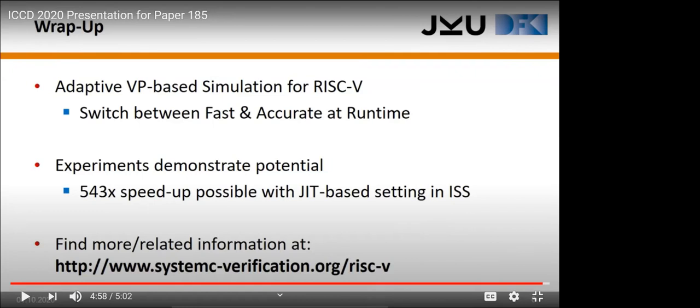Instead of using special RISC-V instructions, we implemented it using the eCall instruction. This one allows you to perform a system call. This is a special instruction for RISC-V, and arguments can be passed through registers. By doing so, we don't need any further instructions, so we don't have to extend a decoder, for example. And this is basically how we implemented it.